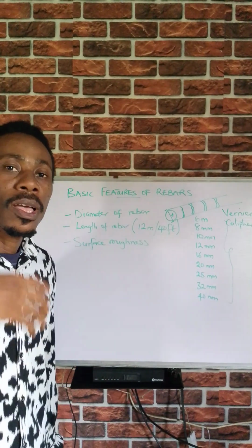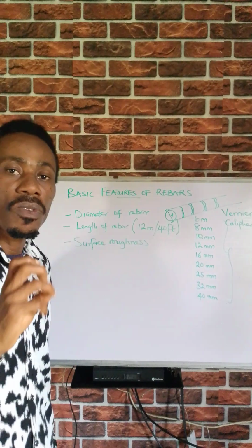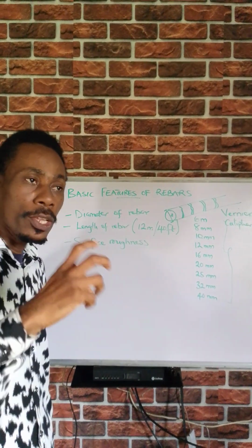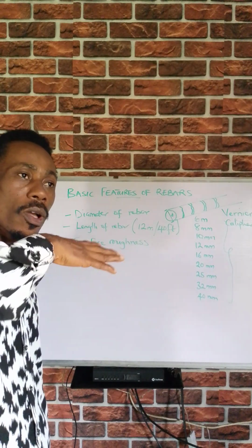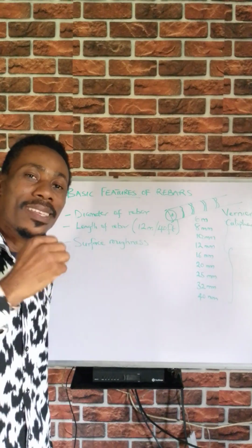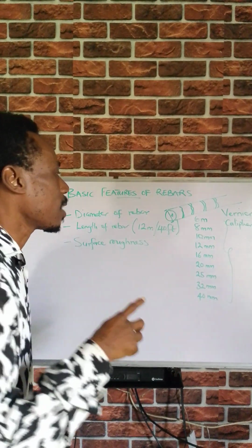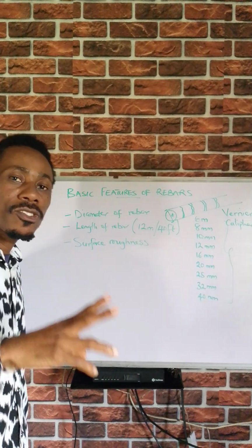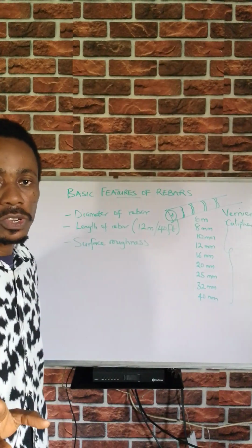All right, so these are some of the things you have to look at, because if you have more of the corrugated surface, it will help to enhance better grip internally, because once the reinforcement is covered by the concrete, there should be this grip that exists internally. You see most times the reinforcement slipping internally, and that can result in vibration or resonance in our concrete structures.